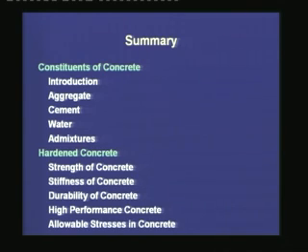These values are needed in the analysis of prestressed concrete members at transfer and at service. They can also be used for the analysis at intermediate loading stages with proper engineering judgment. We have found that the code has specified the allowable compressive stress for flexure at two conditions, one at transfer and one at service loads, and these allowable compressive stresses depend on the grade of concrete, and then the code also specifies the allowable tensile stress. Now, that is based on the type of member that we intend to design.